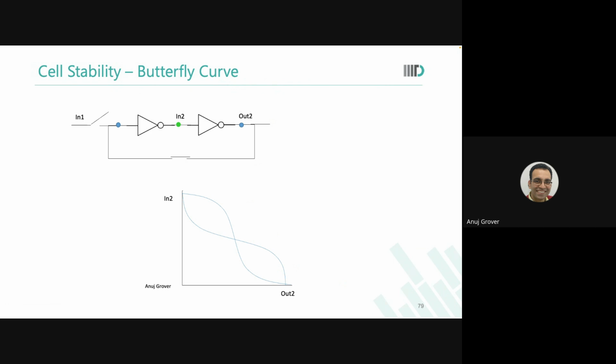You remember we talked about advanced, modern applications where there can be more zeros in a memory array? Now, suppose you know there are going to be more zeros in the memory array, and to reduce the leakage, you design the cell in such a way that there is lesser leakage for zero.